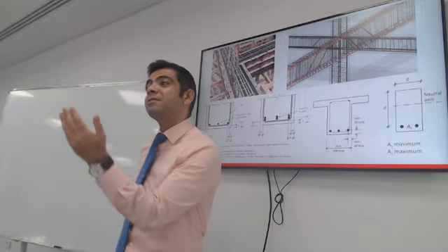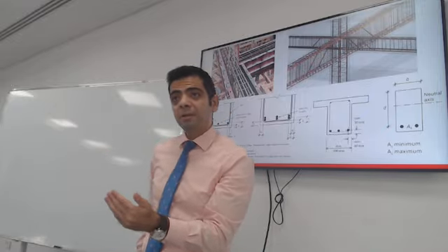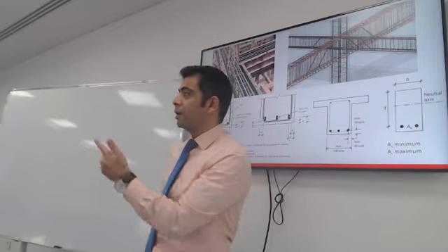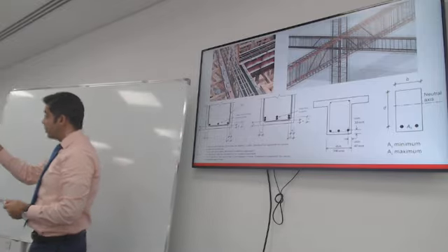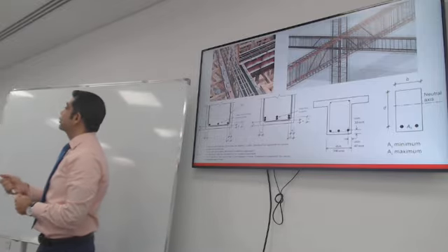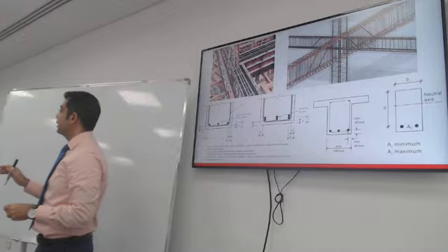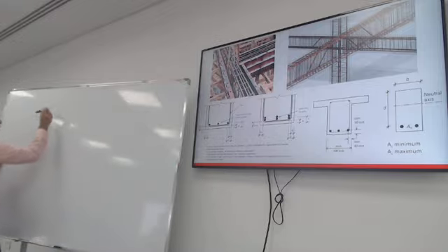What do you expect is the stress distribution for a rectangular cross section? In the very elastic stage, how would that look? Two triangles. Yes, that's pretty much it. If this is the shape of the moment on the section, the top will have compression, the bottom will have tension.